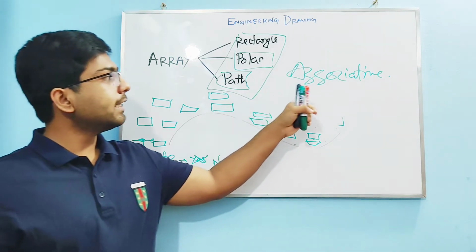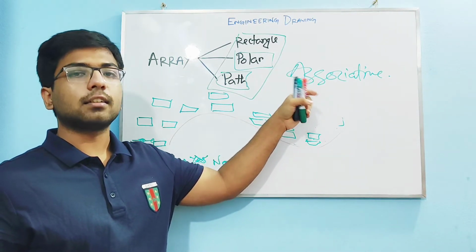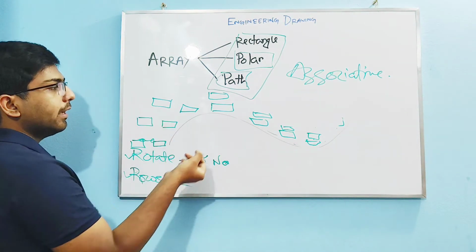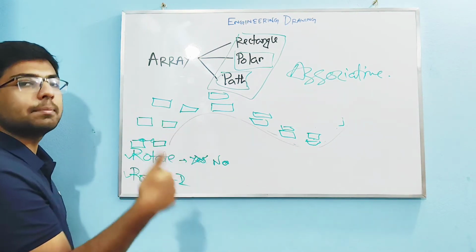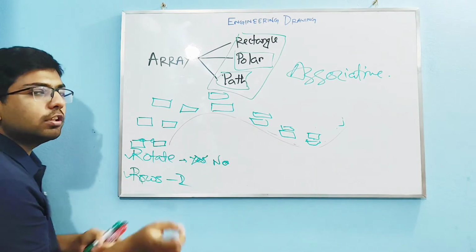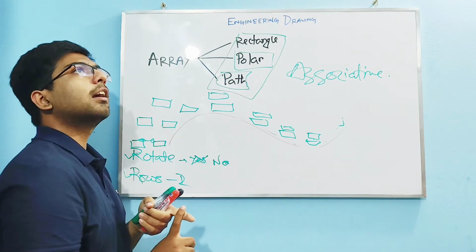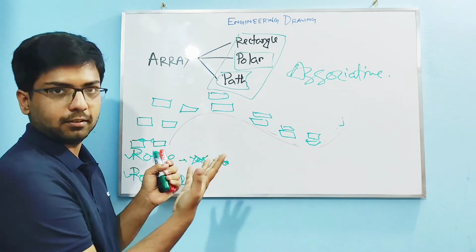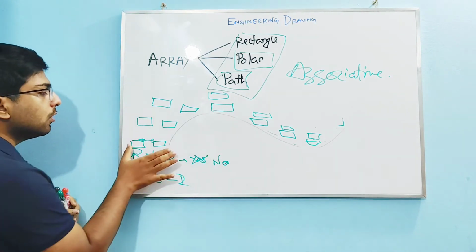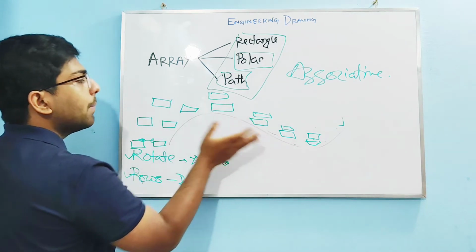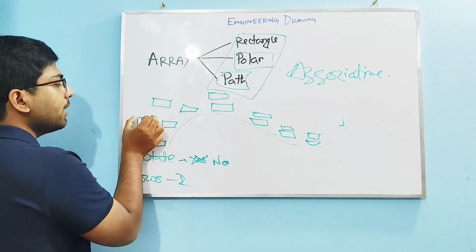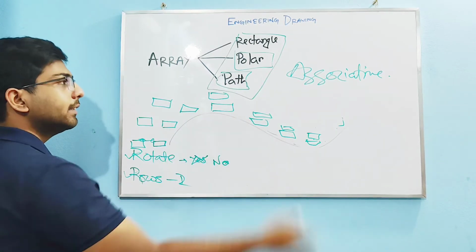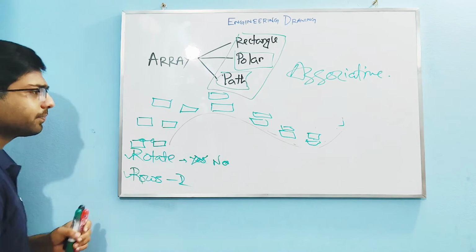But if you turn associative off, then you can select any of these objects separately. Can you remember the explode command we learned about? So it is basically like that. Okay. Previously you could not select these separate objects, but now you can select these rectangles one by one, and this path also. This is the associative option.